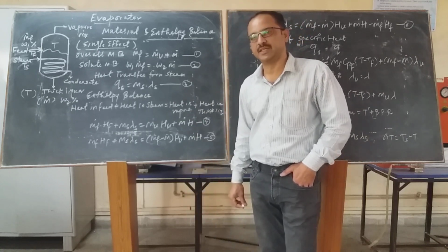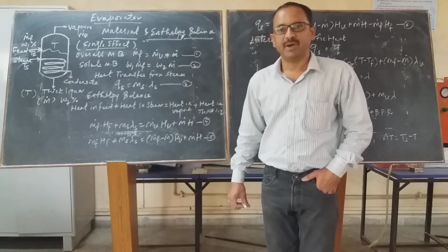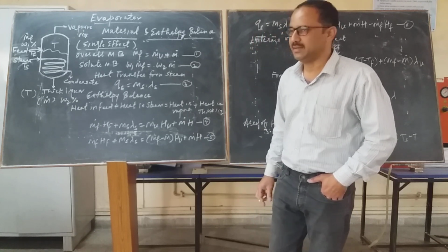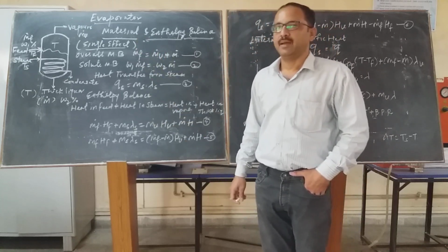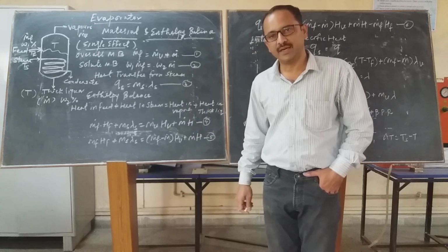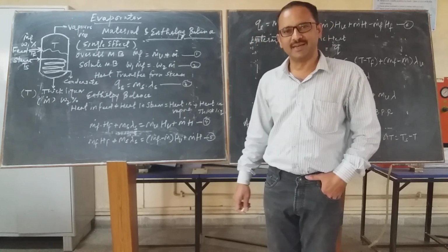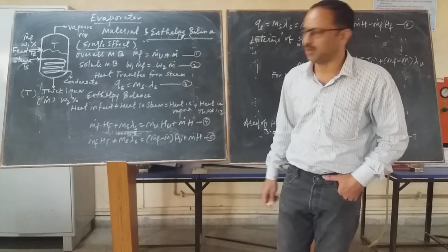Evaporation is a unit operation in which the weak liquor or solution is concentrated by vaporizing a portion of the solvent to form a thick liquor. The feed, in the form of a weak solution, comprises a non-volatile solute plus a volatile solvent. The solvent is generally water, but any other solvent may be involved in the unit operation.